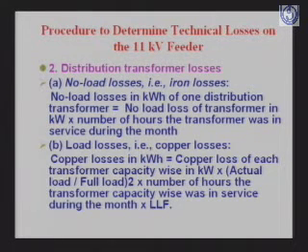And the load losses, that is the copper losses, change with respect to the loading. The losses which are mentioned are full load losses, which will never remain constant. They will keep on changing with respect to the loading. So when you are going to conduct an audit on a transformer, measure the kVA or current, that is the actual load at that time, and what is the full load.